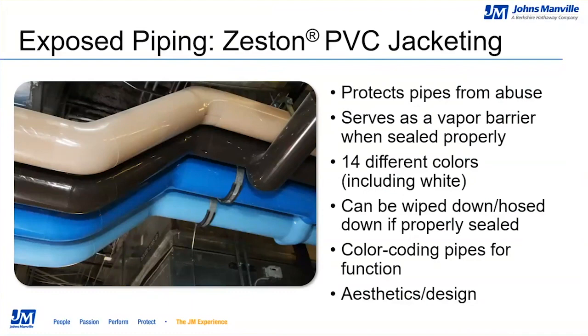For applications like children's hospitals or schools, this variety of colors can be an excellent option to brighten up a space. One of the major benefits of PVC is that it can be wiped down or hosed down if properly sealed. This can be very common in food processing applications. However, keep in mind that the FDA does require the PVC to be 30 mil in thickness for these types of applications. It is also very common to color pipes for function in areas such as mechanical rooms.